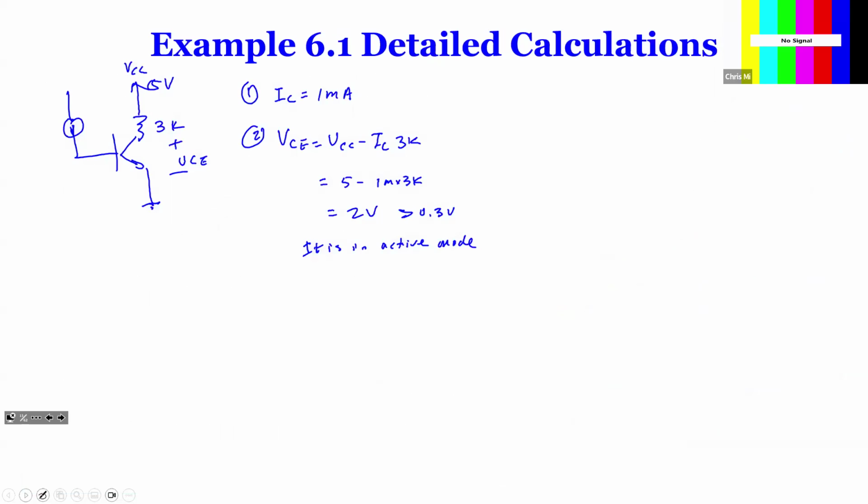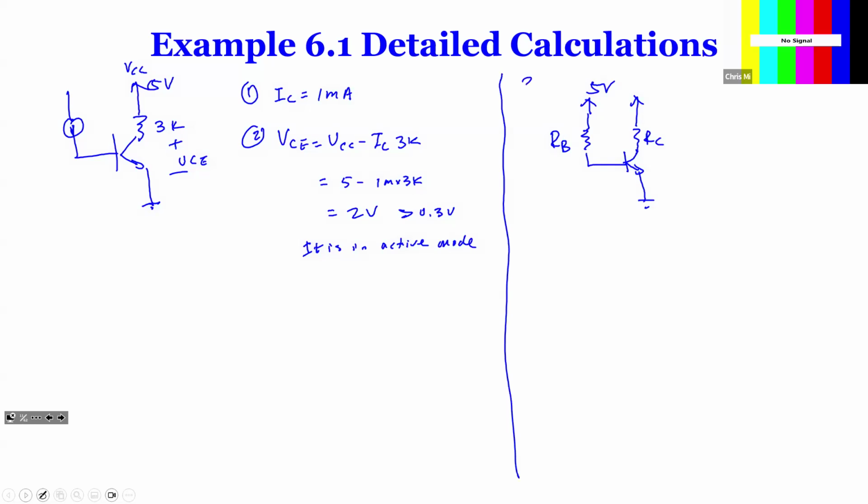Right. So what you're having here is that they're saying this is 5 volts. There's a resistor. So now they're both 5 volts. Okay, so this is ground. And this is RB, because it's RB, this is RC, okay? So what we found already, right? We found VBE already. So VBE was found to be 0.69.